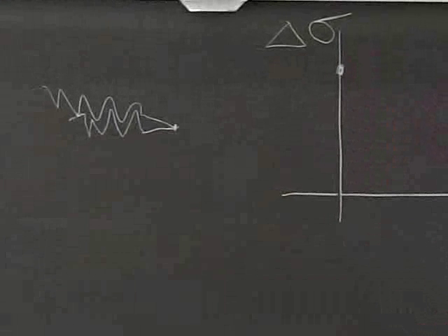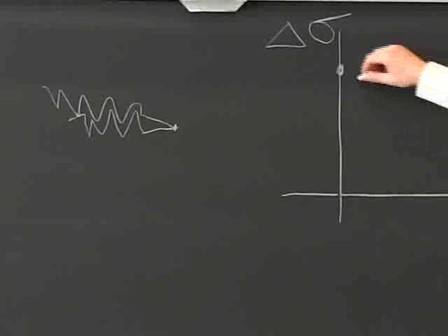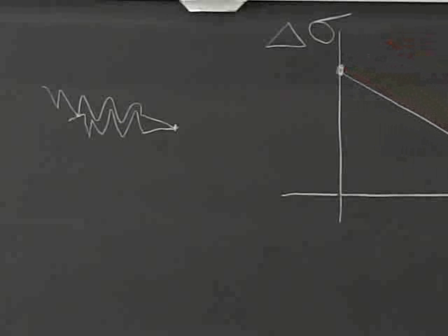And then we do a tensile test. We did another extreme. And then I just said we'll draw a line between them. And that's what Goodman did. And I also added that I wouldn't go beyond the yield here. So I limited that curve, if you will, doing that.